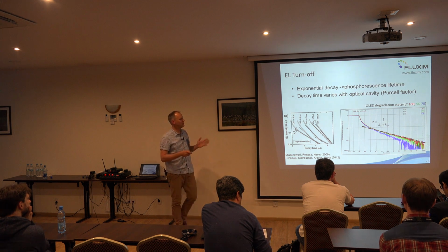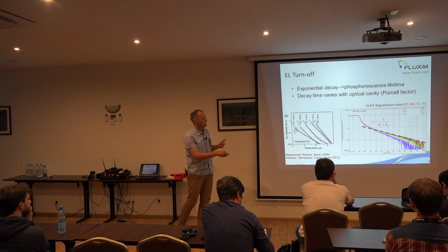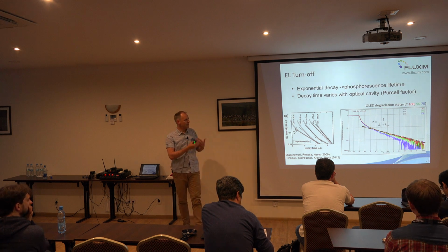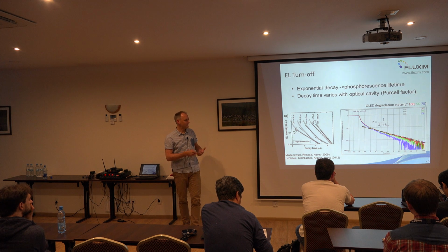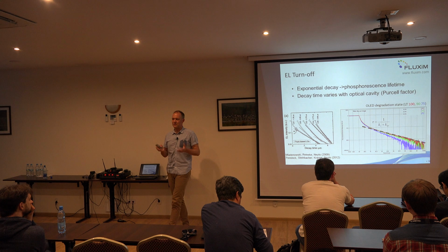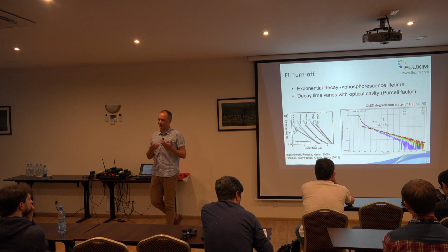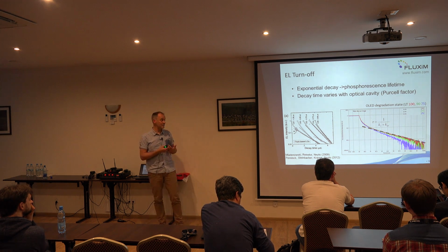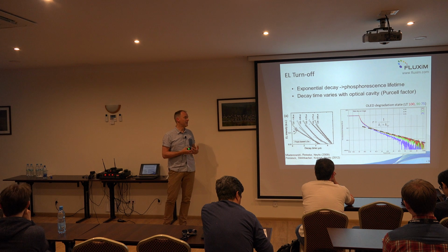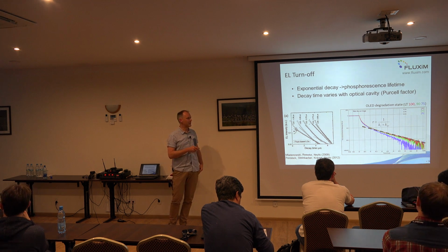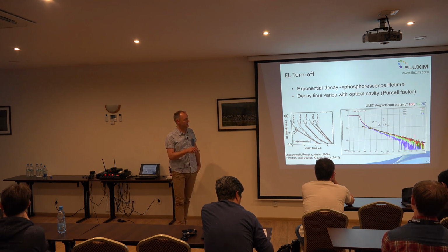We don't really know what, but we see a signature that the decay of the excitons is accelerated. So it could indicate that not only the charge transport layers have degraded, but also the emissive species have additional competing channels to decay non-radiatively rather than radiatively. So you see there's a systematic change between fresh and degraded OLED.